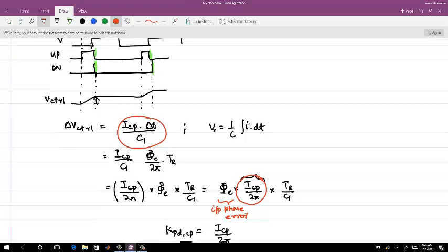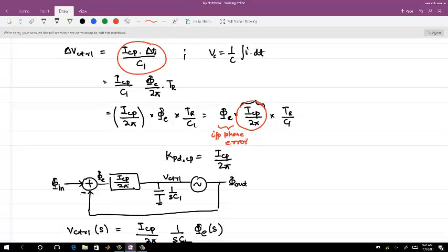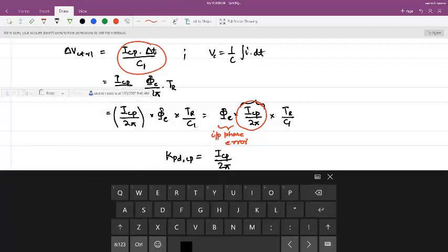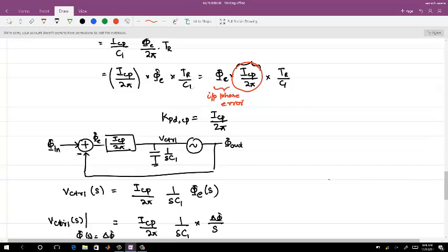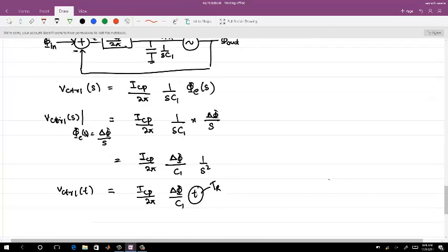I will see if I can explain it in another manner which makes it more clear, but this is working in an average sense. There is no discrepancy between when you start with an absolute time domain picture and when you start with the frequency domain picture and calculate the time domain back. The only relation you need to understand is that the phase error in the pulse width has been averaged over one time period, and the current from the charge pump is integrated for that value.